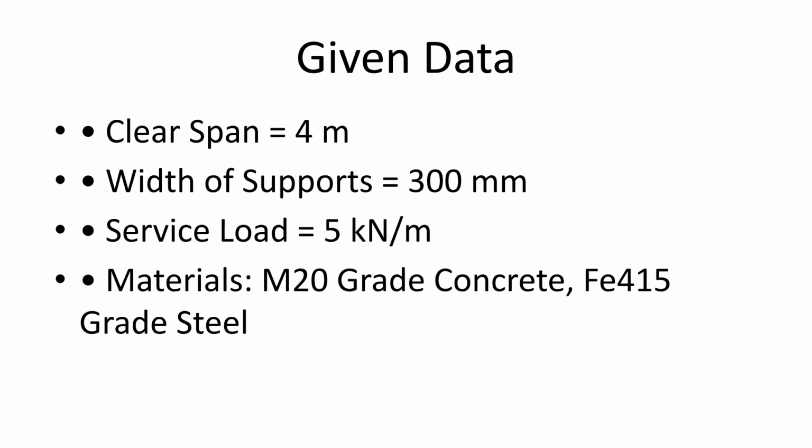Let's summarize the given data for our design. We have a clear span of 4 meters, supports 300 millimeters wide, a service load of 5 kilonewtons per meter, and we are using M20 grade concrete along with Fe415 grade steel for the reinforcement.